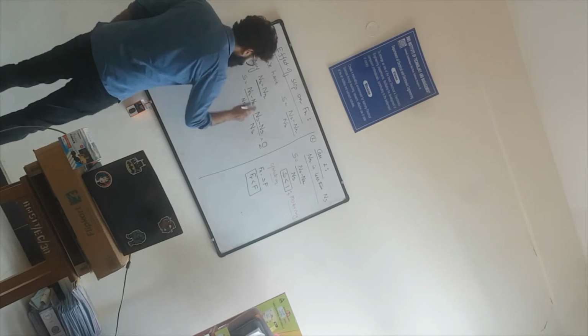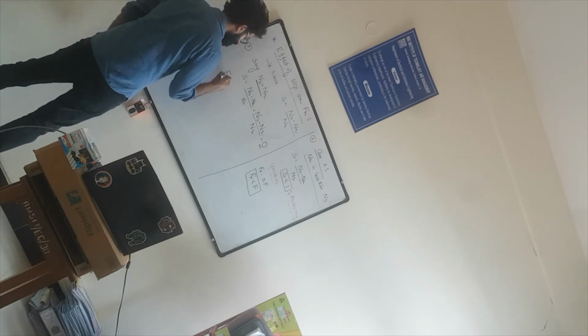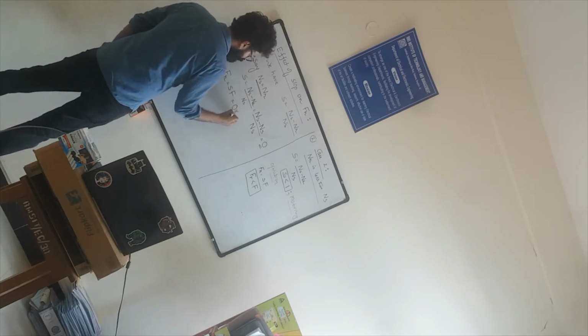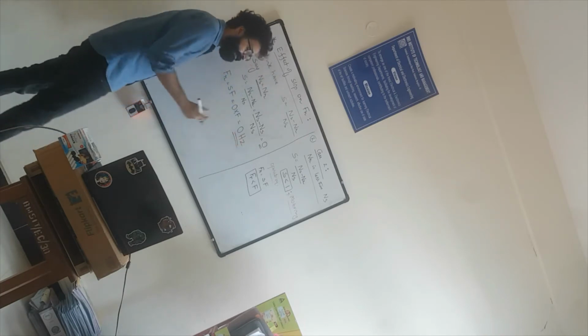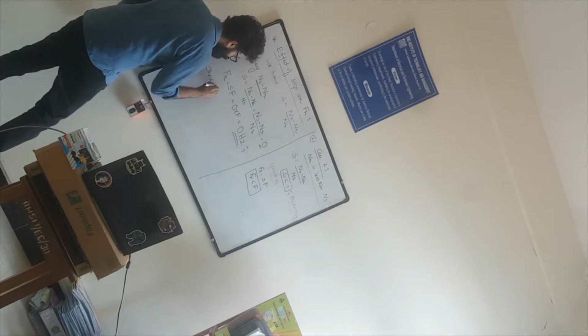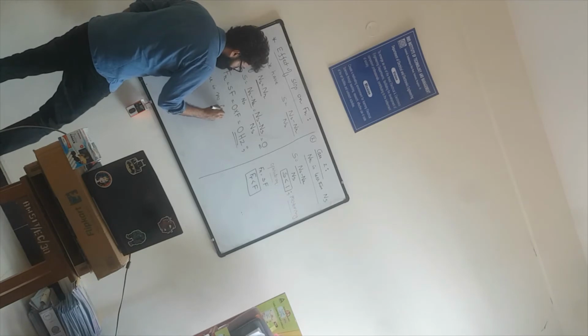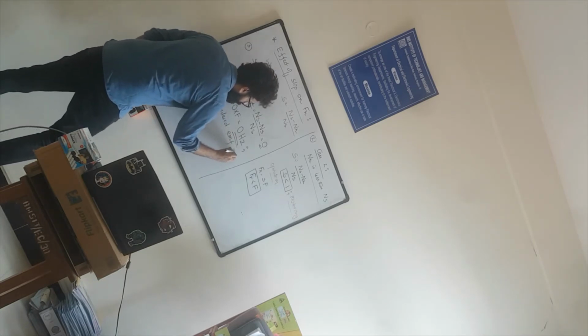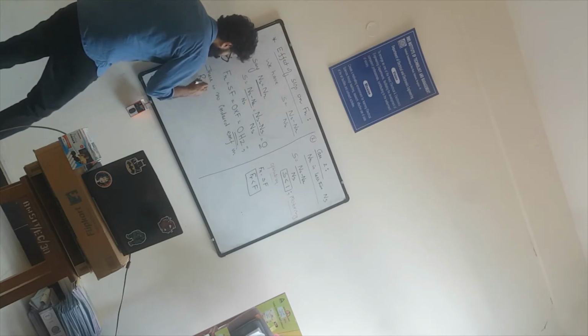Okay. Slip becomes 0. When slip becomes 0, what happens to Fr? The rotor frequency Fr is given as slip times F, which is 0 into F, equal to 0 hertz. What do you mean by 0 hertz? 0 hertz means there is no induced EMF in the rotor.